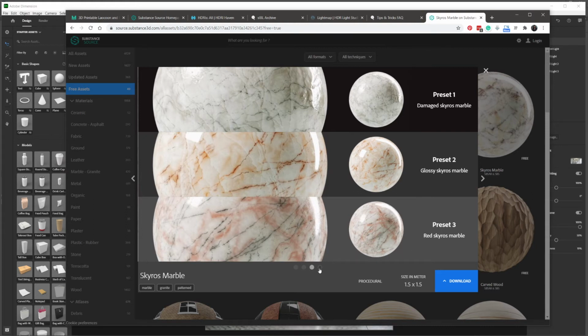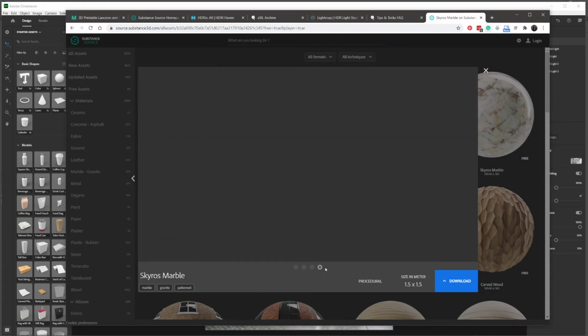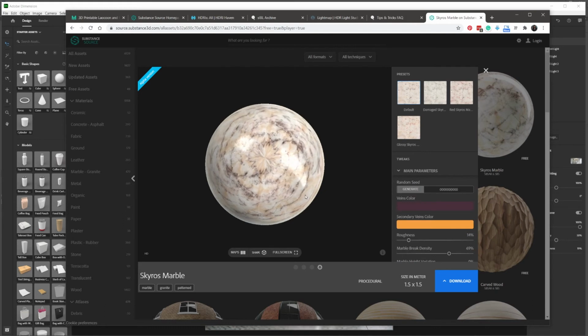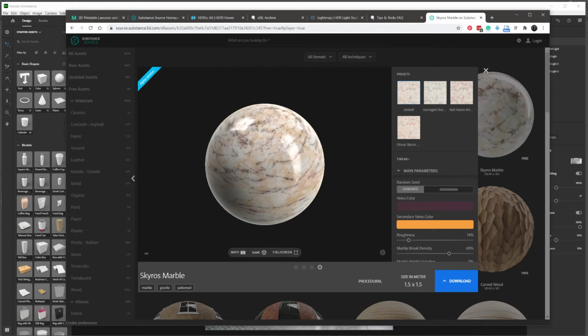But you go to the Substance 3D tab. This is a really cool way to play with the materials before you download them. For example, I can change the textures of it. I can change the colors, the roughness, things that we can do in Dimension, we can do here as well. And when you're happy with the tweaks that you've done, the custom materials that you have adjusted, you can just download from here and make sure you save it as SBSAR, right? So this is a Substance extension that Dimension will recognize.